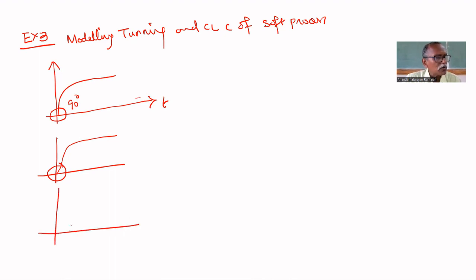As order increases, suppose the order is fourth order, it will be like this. That's why in the level process, you got an S curve. This is called the S curve, reaction curve. As order increases, you will get an S curve. The dead time will come into the picture. Initially, there is no response for some time as order increases.